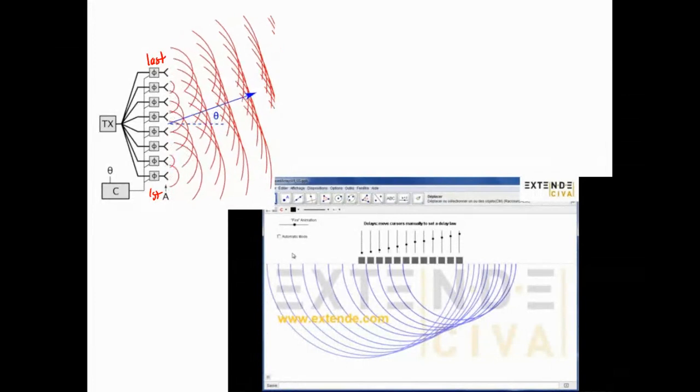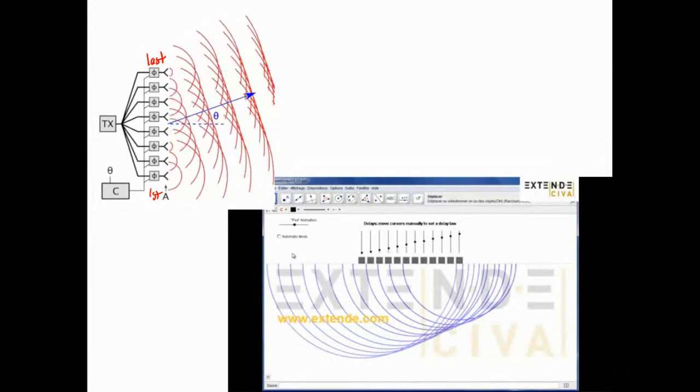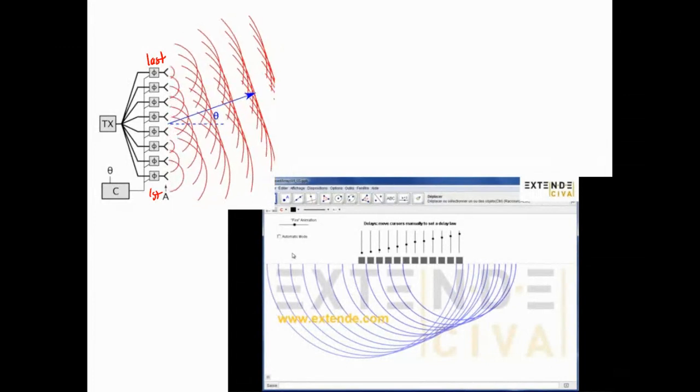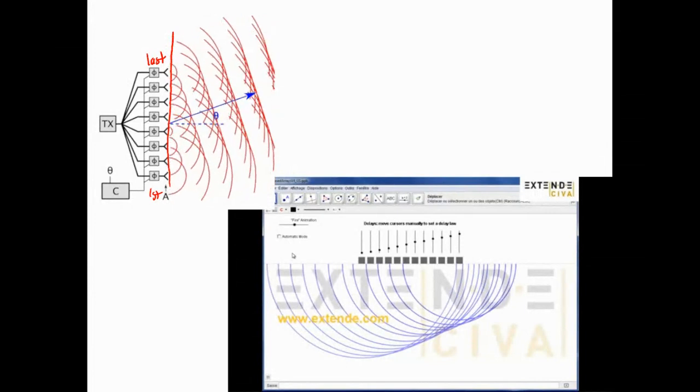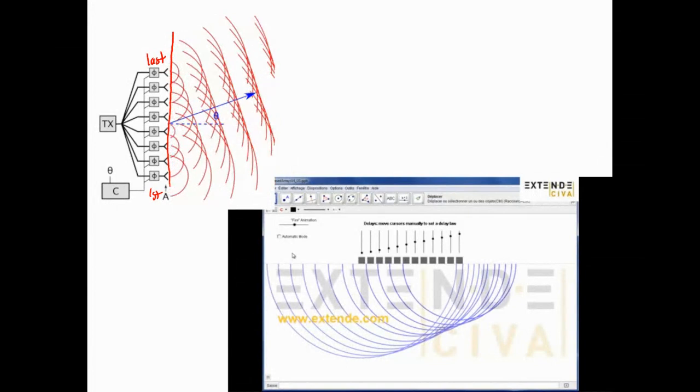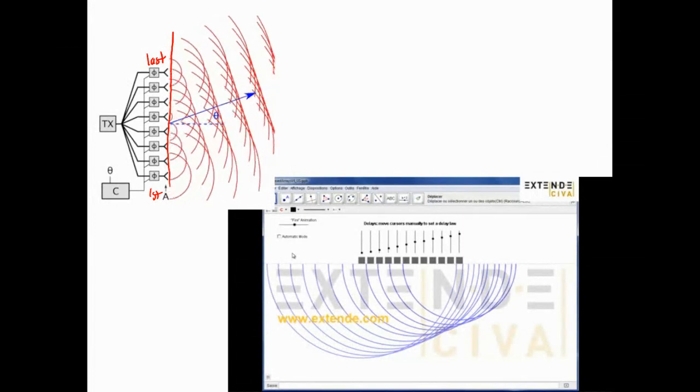You just delay, so phi is the phase. The second one right above it is phased to fire a little bit later, and then the one above that a little bit later, a little bit later. By the time they all add up, you have a beam which does not go straight out, even though the front of your transducer is flat. You're actually shooting off a beam at some angle theta, completely controllable by just the phase, because the wave that goes out is the wavefront addition of all the elements.